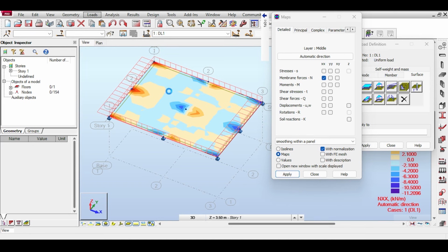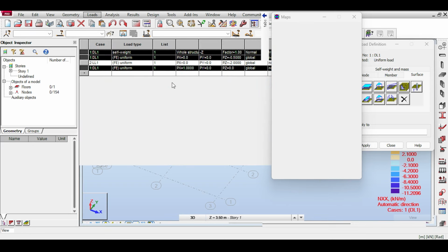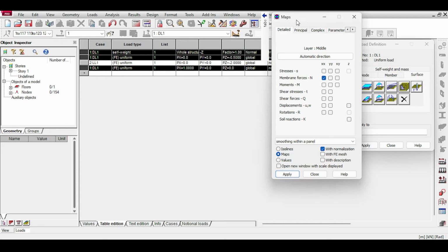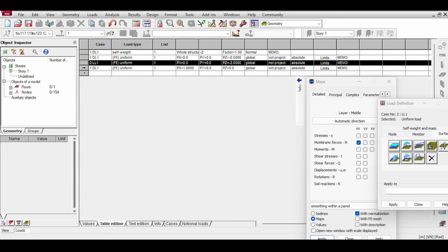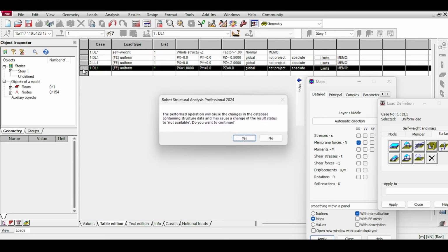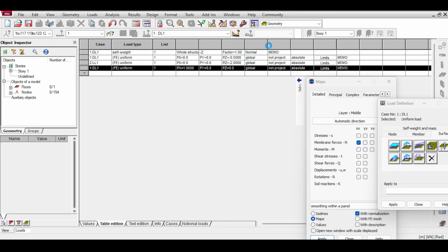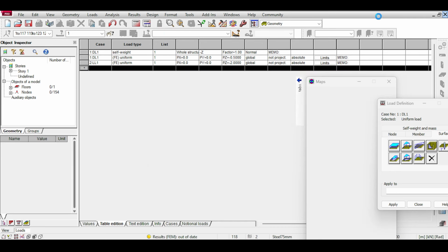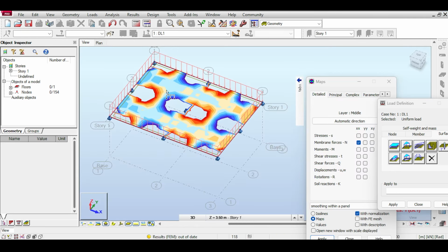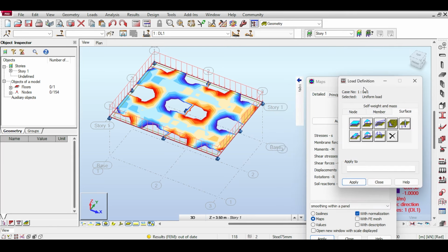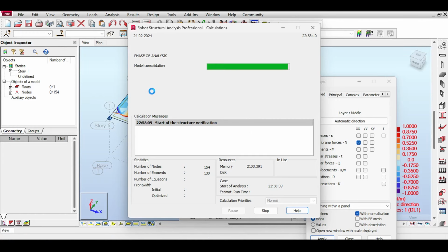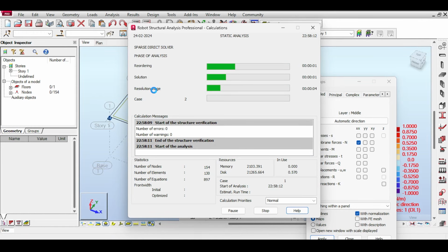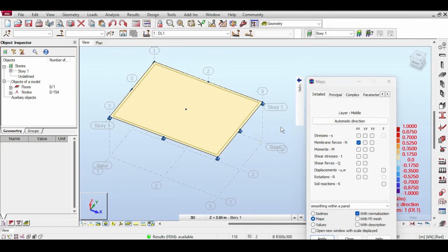Because we are not going to artificially create stresses in the middle layer, I will delete the last load I added. I totally forgot which one it was. Okay, it's this one, the one with the X force. Let me just click here and here, and then push the delete button and basically get rid of the load to get back to my normal force here. Of course, I get gibberish here because I have to perform analysis again. So I run the analysis again to normalize the scales a little bit, and now I get back to nothing in stresses. Fantastic.